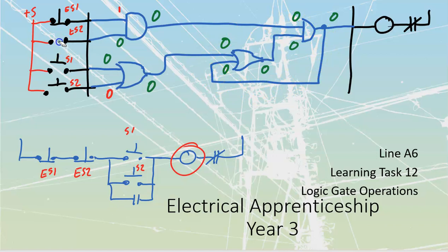As soon as I take my finger back off this button, this is going to go back up to here. This over here would then go and close once again. This over here would go back to high. This would go back to high over here, but we see that our AND gate is still going to be blocking that thing off. And we can do any of these operations as many times as we want. You know, you hit the start button, you're always going to go and turn this thing on. You hit the stop button, you're going to go and turn it off.